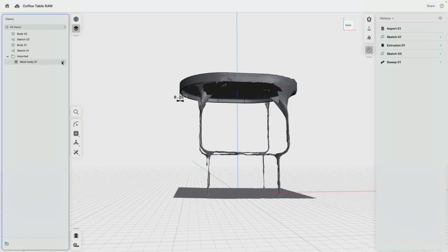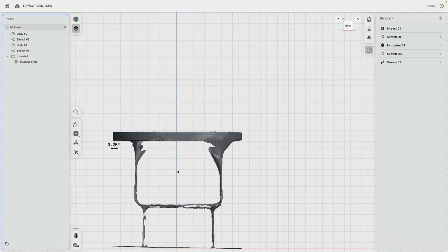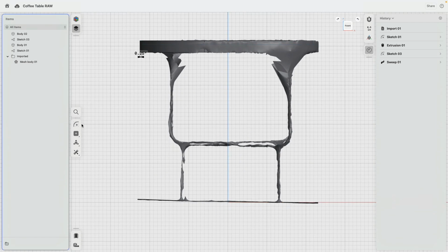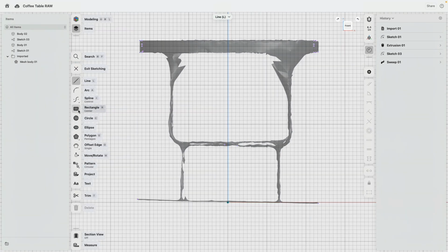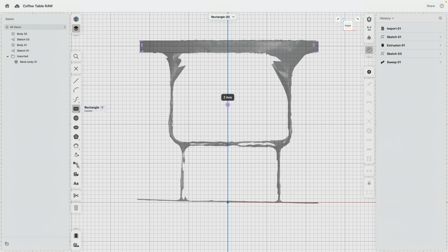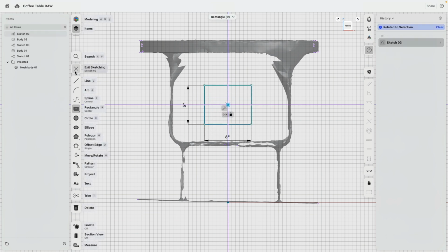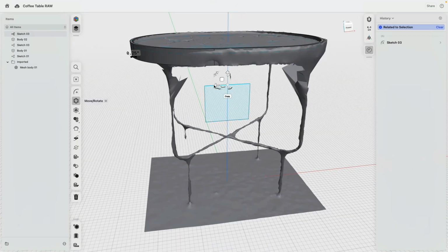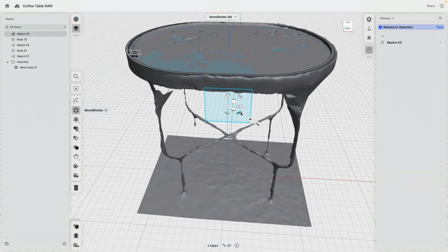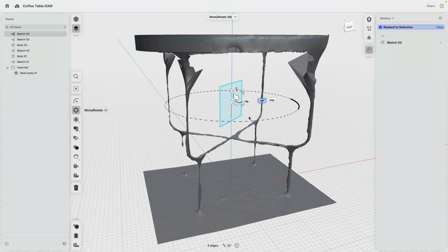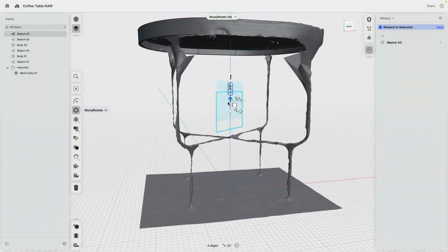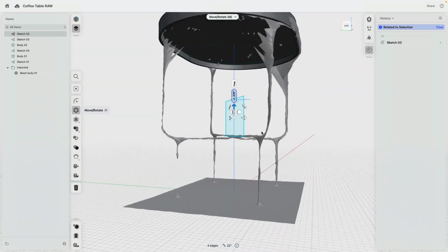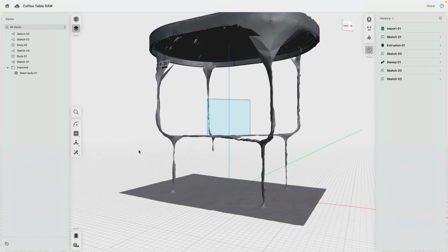How can we do now the legs? They're actually pretty easy. They look complicated, but they are easy. First, in the front view, I'm at the center. I'm going to create just a rectangle. Nothing too complicated. This rectangle, then I would like to rotate, looks like 40 degrees. Now bring this down to there. Cool. Okay.